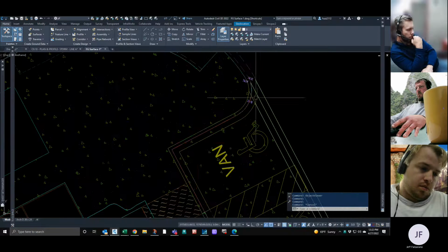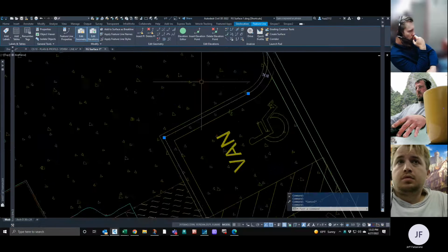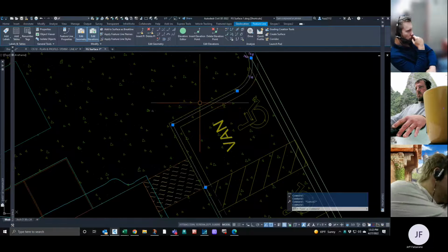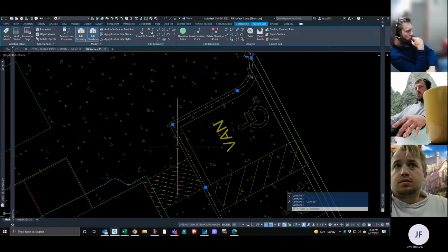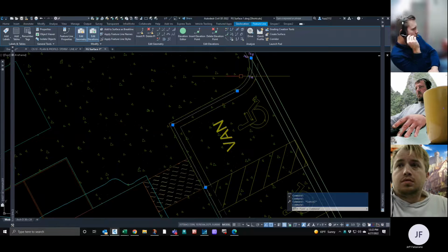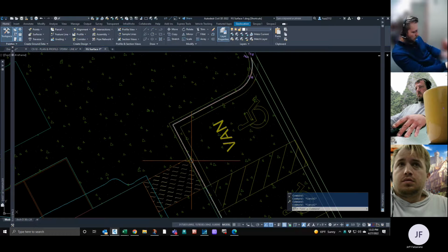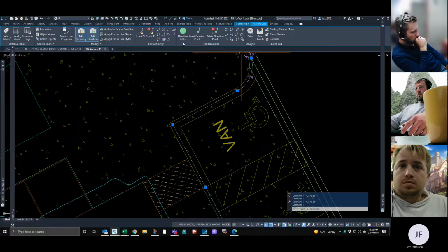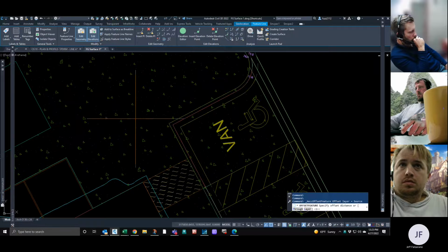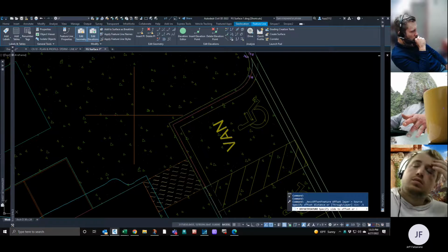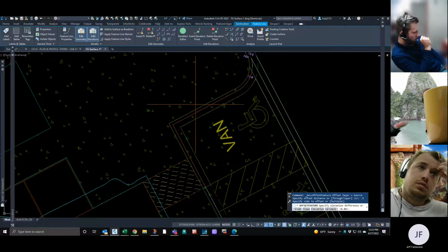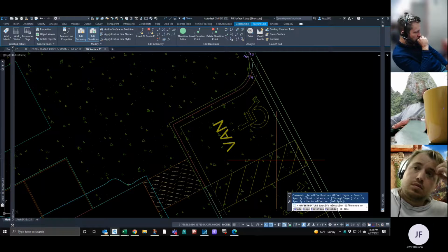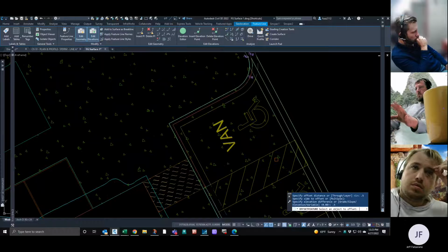So, okay, we'll just have to take this line now, and we're going to offset it 6 inches up and put in this backup curb. So let's just highlight this feature line here, do another stepped offset. You want to go 6 inches, so 0.5 is the distance. We want to go on this side. Elevation difference is going to be a 0.5. So there is our backup curb.